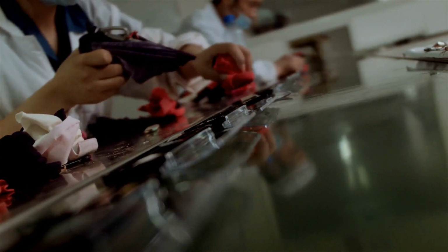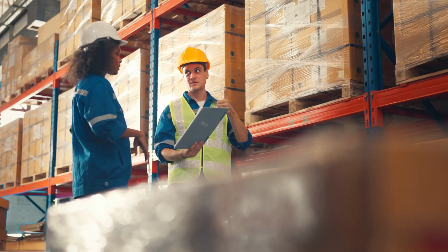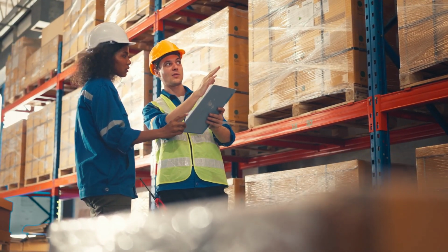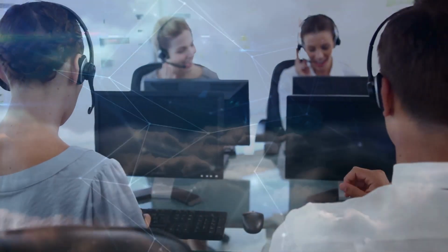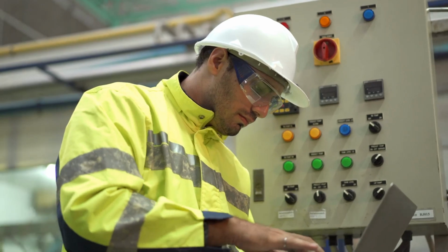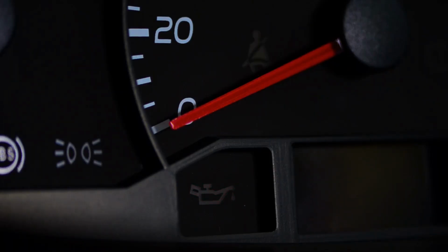Before solving the root cause, we must protect the customer. Discipline 3 calls for immediate action to contain the problem. These actions don't solve the root cause, but they prevent further damage. Examples include placing product on hold, implementing 100% inspection, communicating with customers to mitigate field risk, and adding temporary quality gates. Containment should be verified to test your short-term fix. Is it truly preventing recurrence? If not, you may be multiplying the problem under the radar.